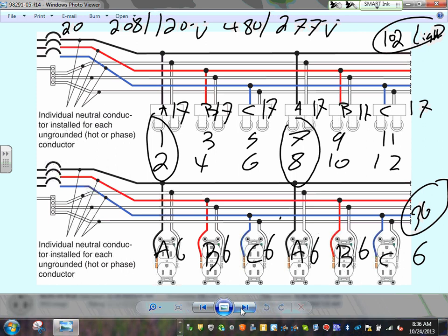Again, that's design-wise. You can go code-wise. You can go up to 13 receptacles in 1 circuit. Any comments? Any questions, guys? How we circuit 3-phase? I can't emphasize this enough. So that's your receptacles and circuiting.